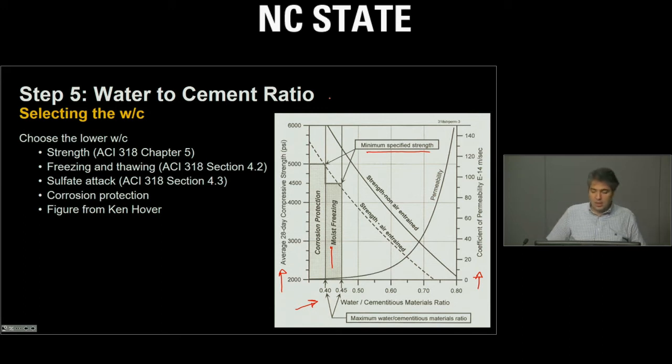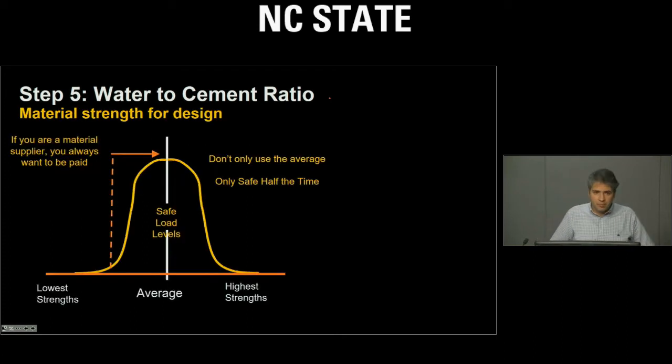So this is just a schematic illustration of the information. The additional thing that I will show is that with increasing the water-cement ratio, the coefficient of permeability increases very rapidly. And again, this is because of all the leftover water, all the big pores inside the system, so the permeability of the system increases very rapidly with increasing the water-cement ratio.